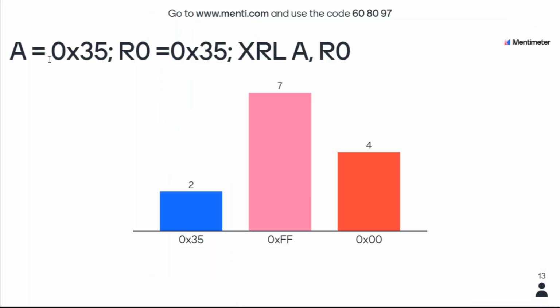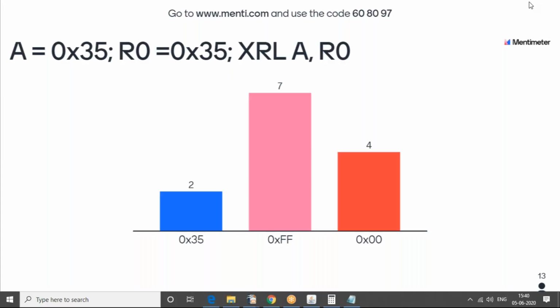This is one of the interesting properties of the XOR gate. It is always used to clear a register. If you don't know the content of the register, you can copy that register to another place and then XOR it with that same register, and it will always go to 0. Or you can XOR the register with the same register again, and it will again go to 0. So that's one way to clear a register. I thought that was an interesting question to ask.